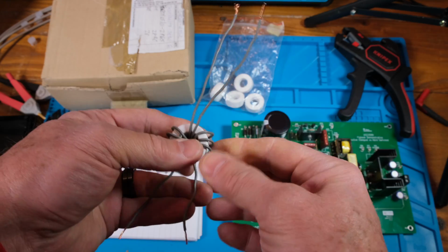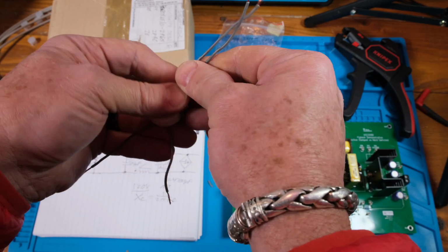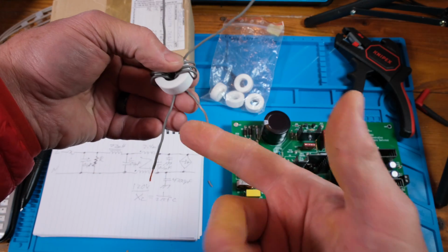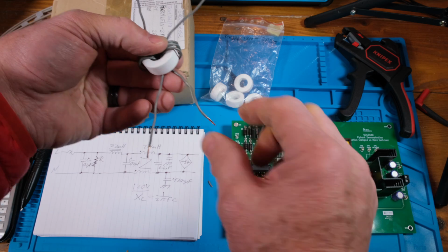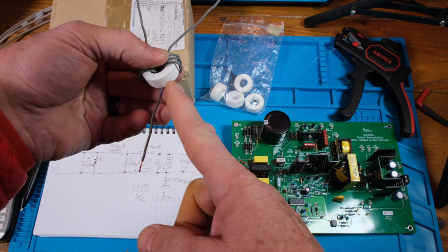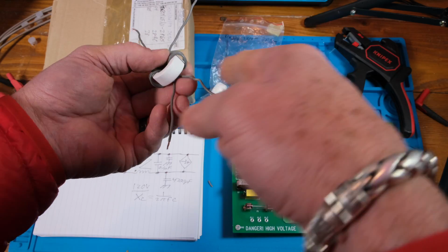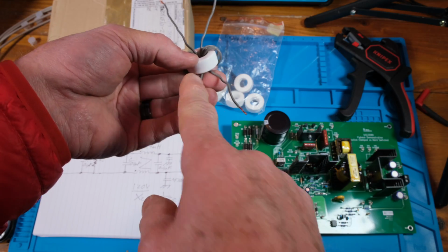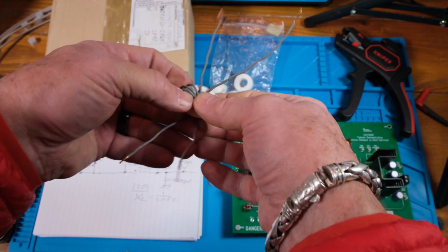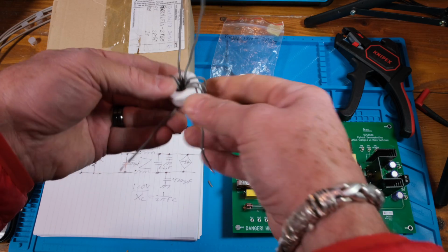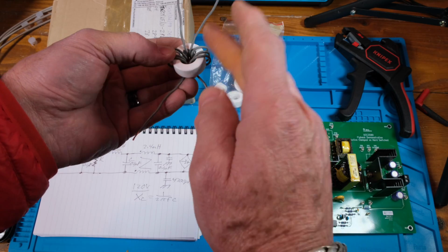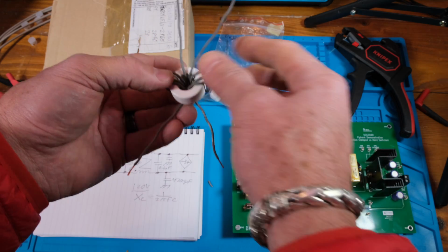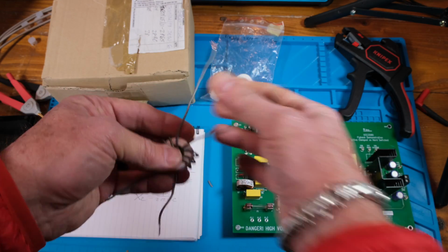So it becomes kind of obvious that they're wound in opposite directions, right? So when the current comes in this way, it builds a field this way. And then when the same common mode signal comes in this one, it goes the opposite direction. So they're canceling the field on the core. So if it's common mode noise coming in this way, the 2 fields cancel. That's what we want, okay?